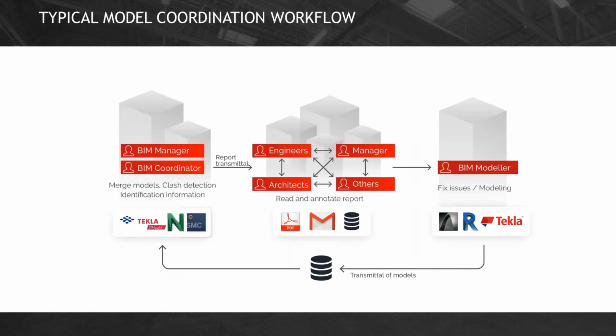So let's take a look at the typical model coordination workflow that we see today, where you've got your BIM manager, BIM coordinator, VDC coordinator, using tools like Navisworks to pull together multidisciplinary, federated models, do visual validation or possibly a clash detection report of areas of concern, and then either save viewpoints or send some type of transmittal off to the design consultants around areas that they need to address and fix regarding the design. Inevitably, what happens is there's a lot of back and forth communication between the engineers and, say, architects around things that they're working on, traditionally through emails, maybe markups or PDF files.